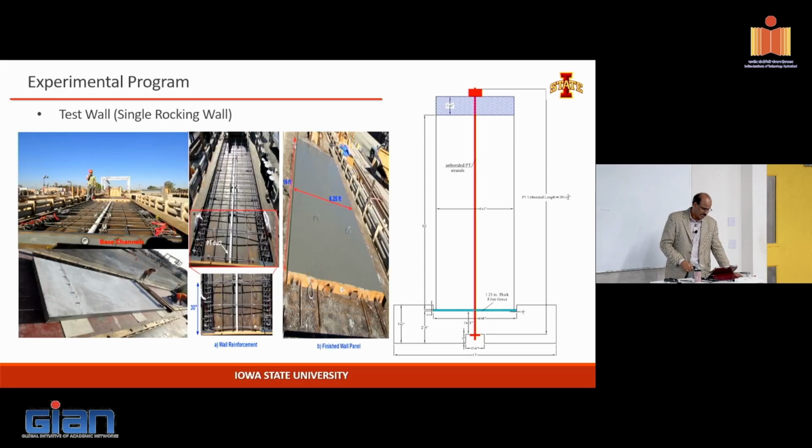So here's a casting of the single rocking wall. What I want you to focus on here is that if you are casting the single rocking wall, they're going to rock. The resistance comes from at the base, basically, post-tensioning and compression. And the amount of reinforcement you need, so that applies in every section, you really don't need much reinforcement in the structure.